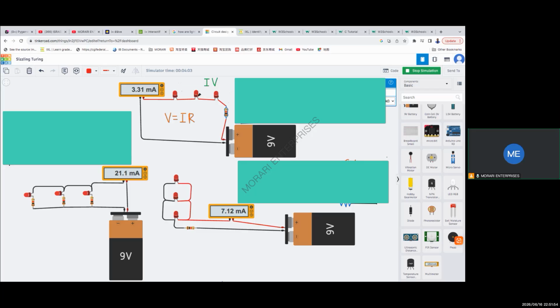Now, if you keep this circuit open for 1 hour, we will take that power and multiply by 3,600 seconds in 1 hour to know the energy that each LED will consume in 1 hour. So from current intensity to resistance to voltage to power to energy, those are the concepts that we can learn from an electrical circuit. Of course, that energy is called electrical energy.